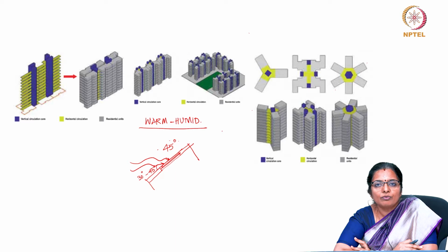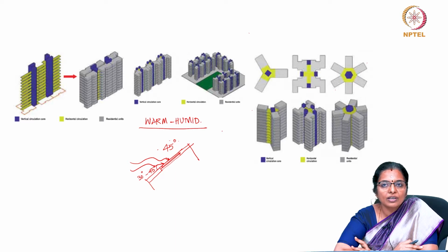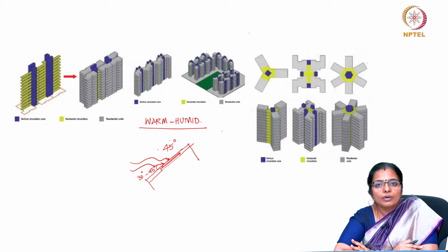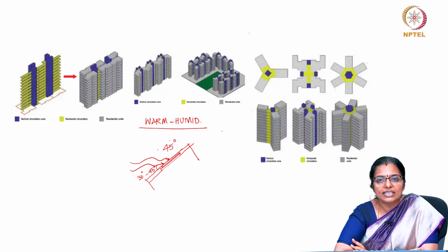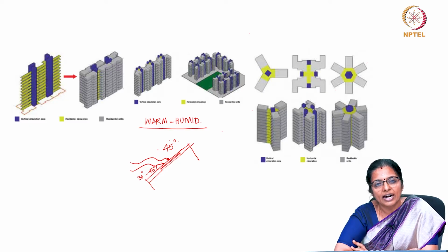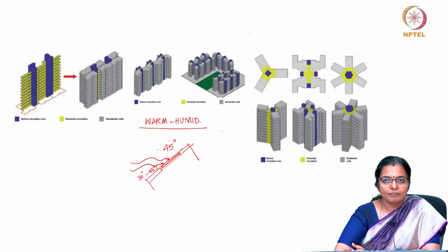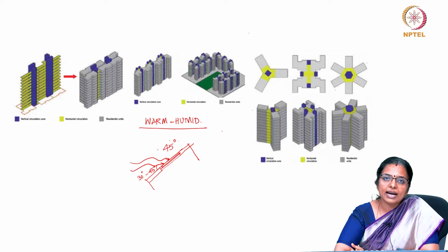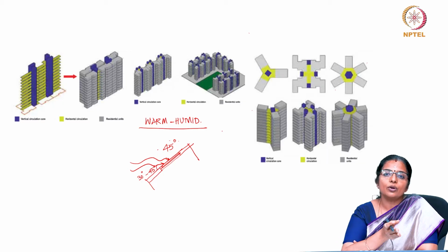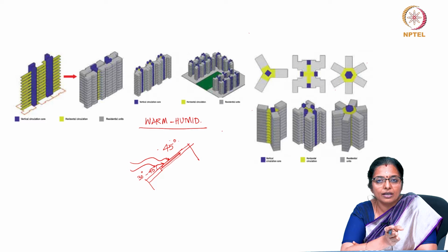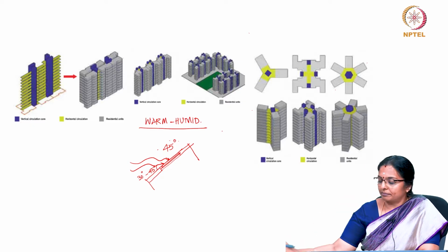As a general rule, with low-rise buildings where the walls would not receive much radiation, orientation according to the wind direction is more advisable. So, if you look at the form, the preferences of typologies for multi-storied residential buildings, you must try to have the form in such a way that you are able to tap breeze and you are able to cut off solar radiation, or at least have a via media where you cut solar radiation and bring in breeze.